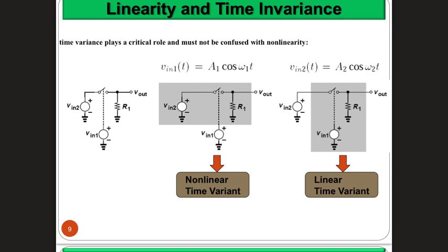So we're discussing this system in terms of checking the linearity and the time variance. And we found that if you consider Vn1 as the input and V out, while you consider Vn2 something internal to the system, you end up with a non-linear but time-varying system. If you consider Vn1 as internal while Vn2 is the input to the system, and the same output is measured, then the relation becomes linear, but the system also, in that case, stays as time-varying.